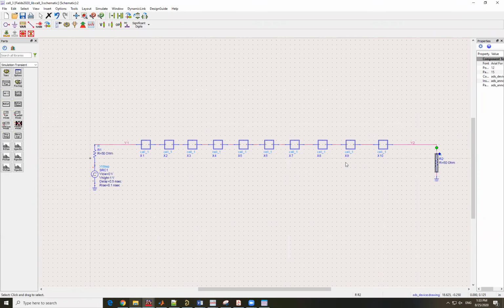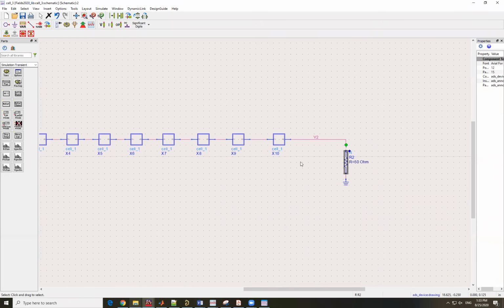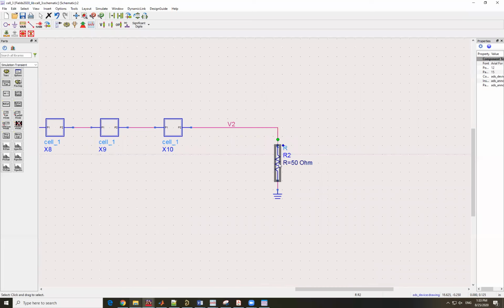If we don't want to have it, you just click on it. You want to make it not work, either delete it with the delete key on your keyboard, which I recommend, or you click on this, which deactivates the resistor. Okay, this makes the resistor deactivate. Don't use this one. It will make it short. This will make it open. This one will make it short.